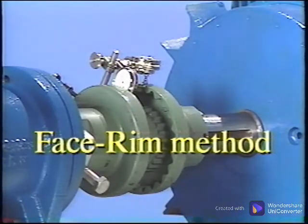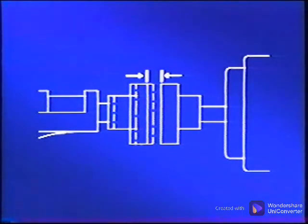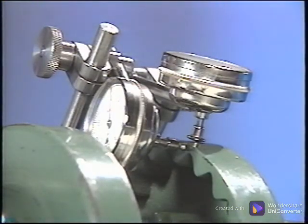The face rim method works well for short spans, and it is easier to visualize the readings. The disadvantages are that it easily becomes a trial and error process. Any axial shaft float will induce error in the face reading and affect the angular misalignment calculations, since this face reading is used to determine the amount of angular misalignment.